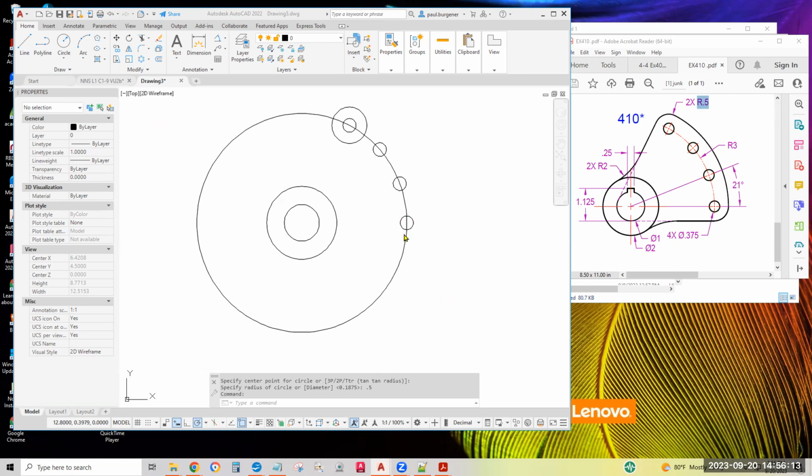We got to make a 0.5 radius circle around this bottom bolt hole. Click on circle center radius icon. Snap at the quad. Whoa, what happened there? Okay, snap at the quadrant of the big circle or the center of the 3/8 circle and create a 0.5 radius circle.